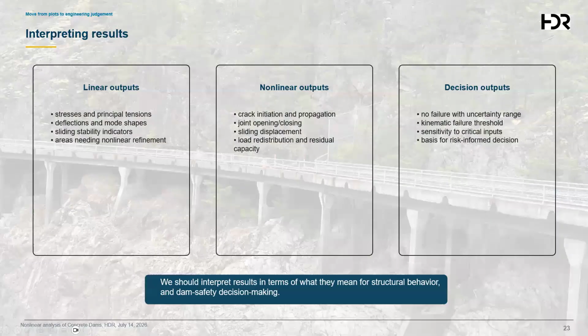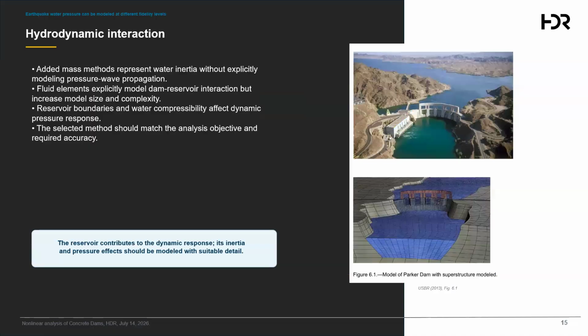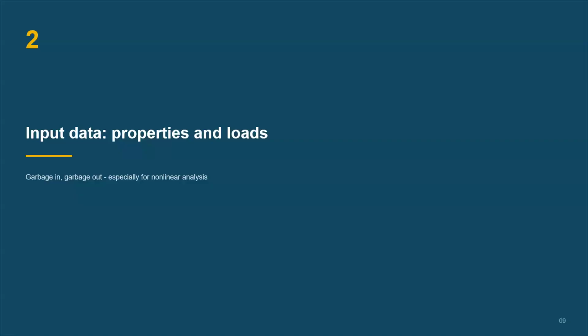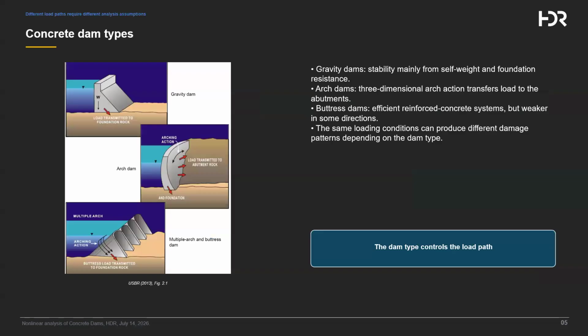The buttress dam, as I showed you, the bottom one, multiple arch or buttress dam, as they call it, has some reinforcement and a layout of reinforcement. But for gravity and arch dams, which are the ones commonly used, we don't have any rebar. We just have mass concrete.